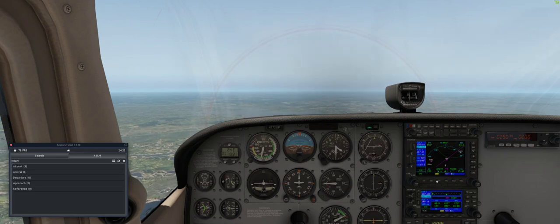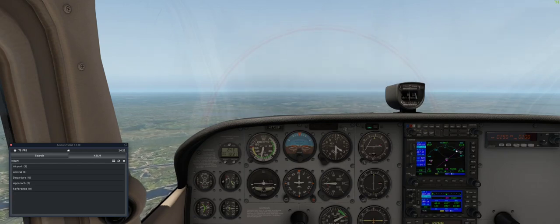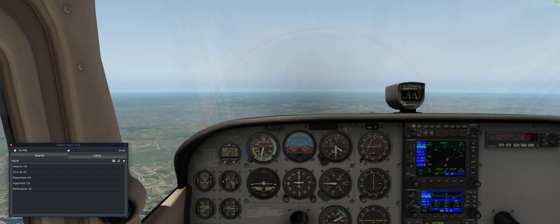You can fail to do that. You can ignore these messages. Oh, it's saying 52. There. And what does the message airspace near and here? Near above? Well, we're about to cross over an airspace, which you should make contact with air traffic control and be under air traffic control. But we're not doing that today, so we're just going to ignore it. That's the point of those messages. You can have this set completely wrong, and the autopilot will continue to follow point to point.